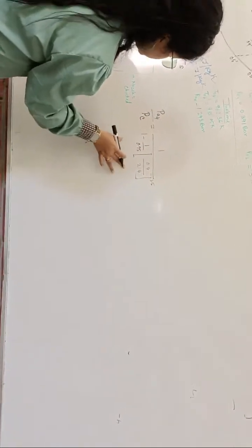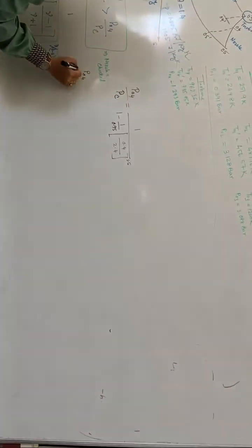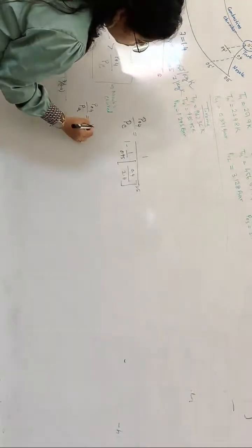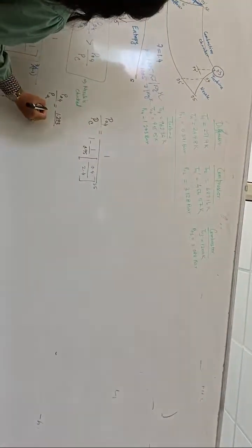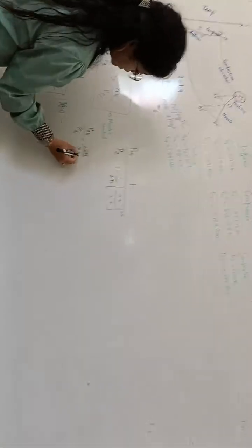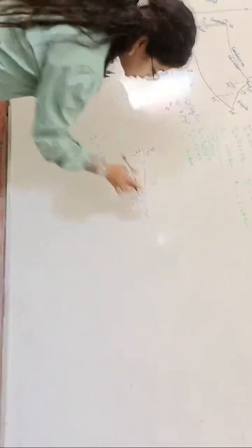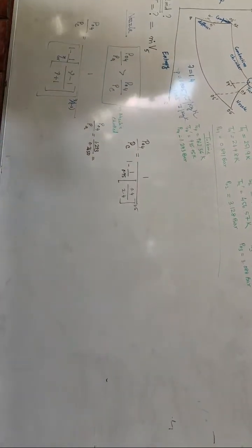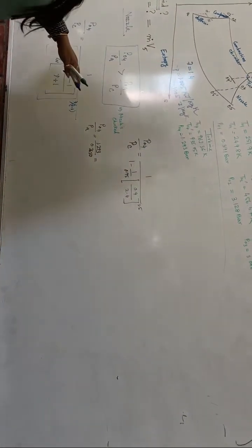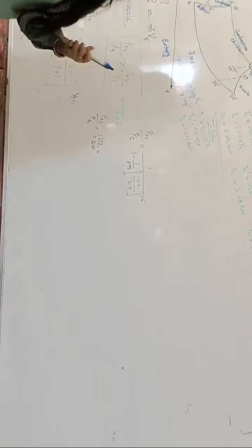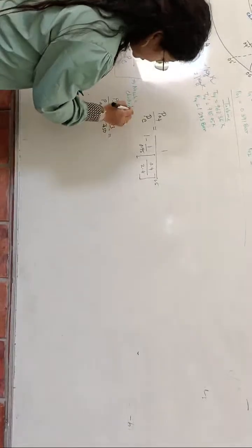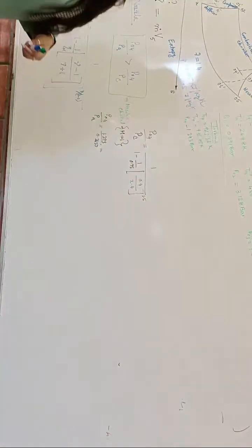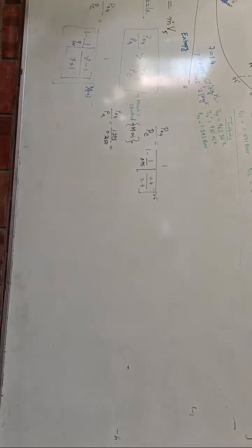So quickly solve this and check the ratio of P04 by PA. What is the P04 by PA? 1.293 by 0.2650. Quickly check this value and the other value and you can find whether the nozzle is getting choked. And what is the meaning of the nozzle getting choked? That means that at the throat section, the Mach number becomes 1. If it proves that it is choked, that means Mach number is 1 at the throat section of a nozzle.